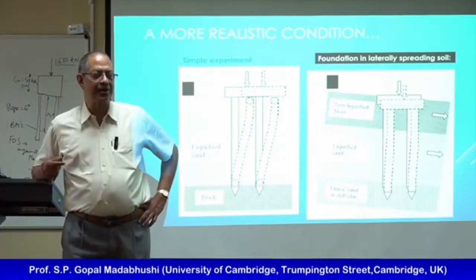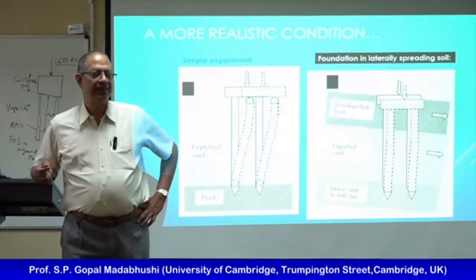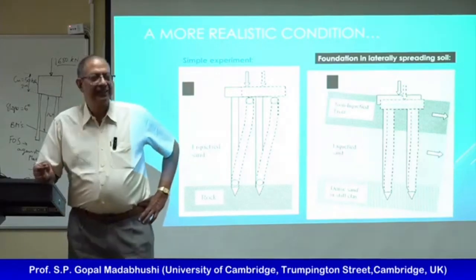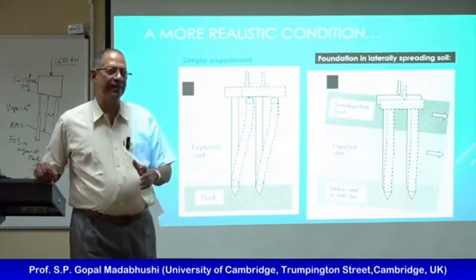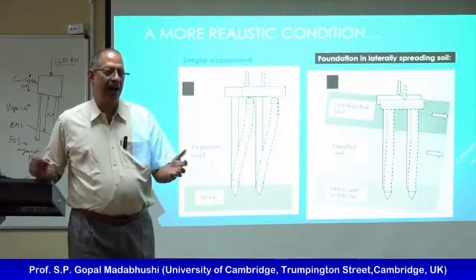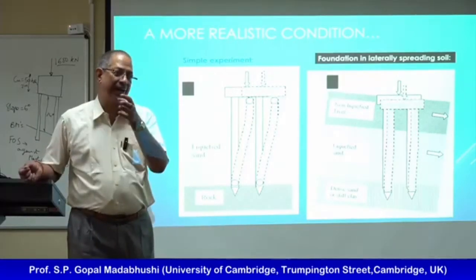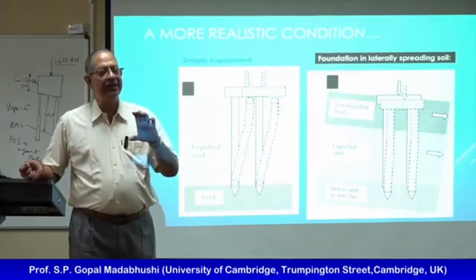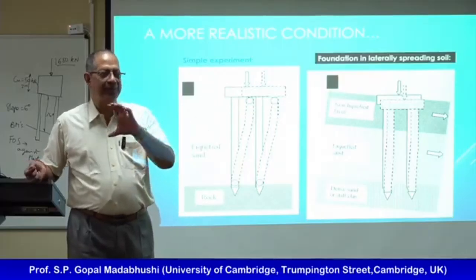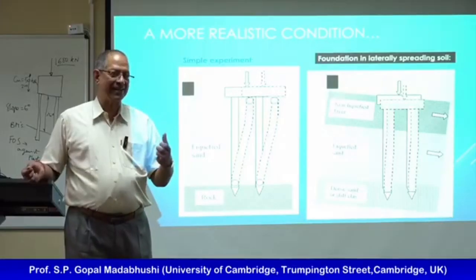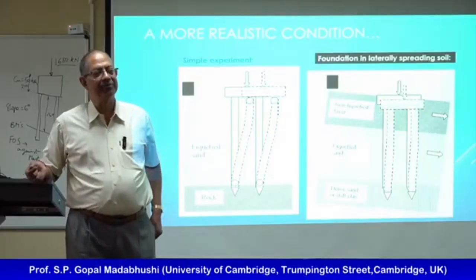Are you talking about post consolidation? Like after a week maybe. Yeah, okay, you're talking about post reconsolidation after the liquefaction. The belief is yes. In fact, if anything, you'll get better because if it is sand, it would have densified, right? So you'll get better resistance than before.